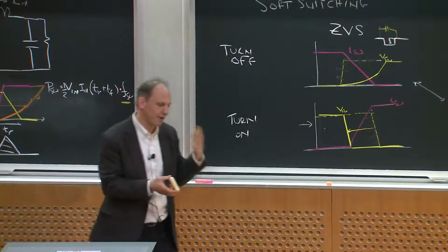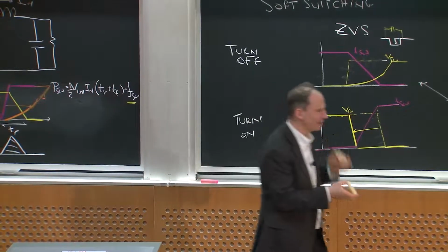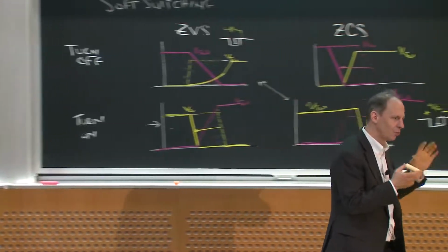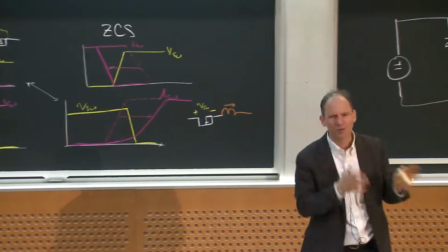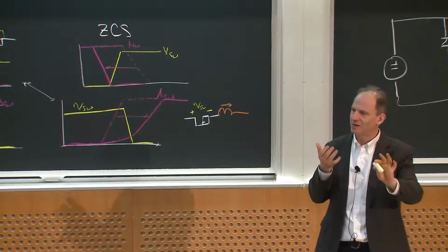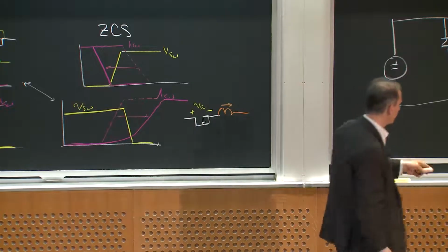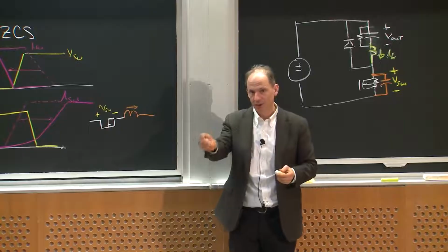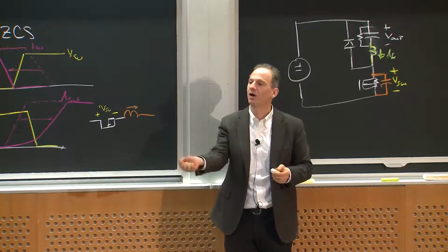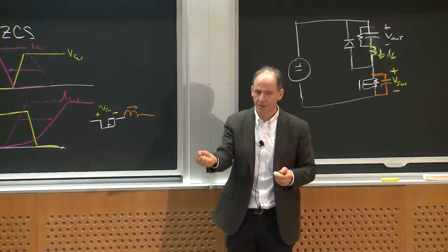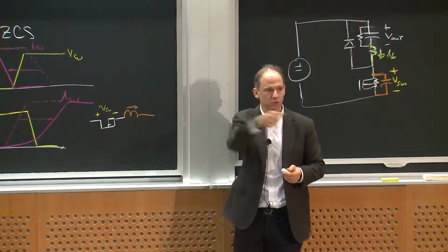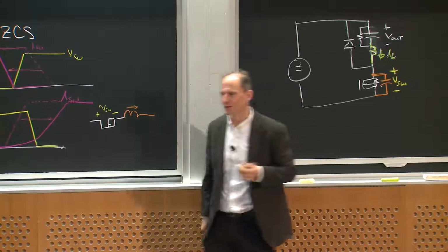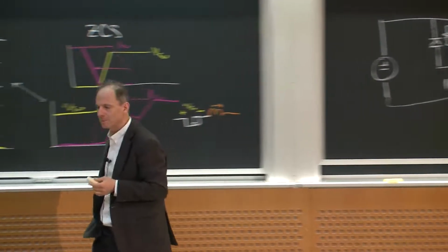And I should say, by the way, I'm pretending that the device capacitance is a lossless capacitance. Were that it were so, but you actually get some loss in that capacitance. So sometimes you would like to use a high-quality external capacitor so that that ring down is less lossy than it would otherwise be. But in this case, we pushed up the switching frequency so far that we could just do it with the device capacitance. Okay?